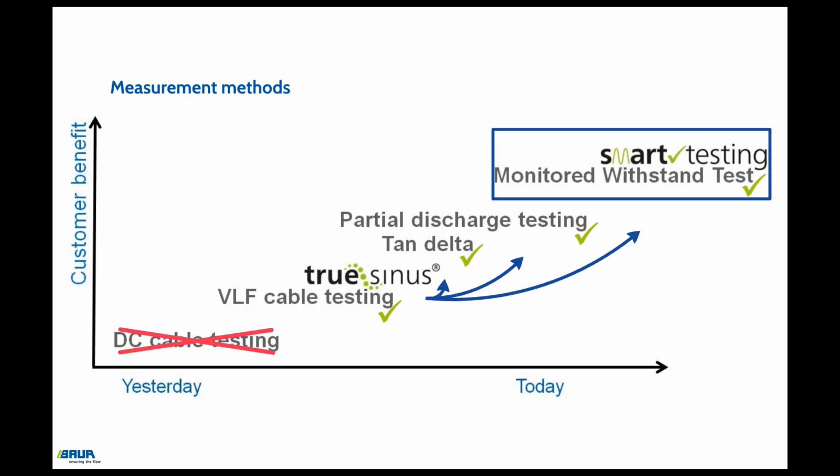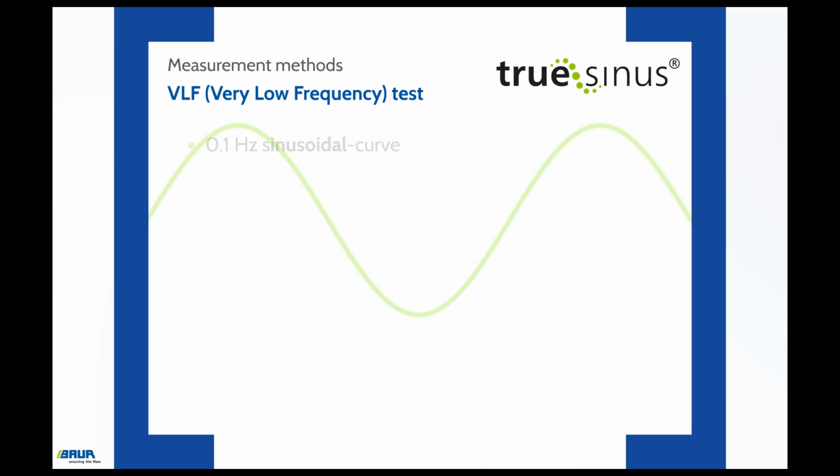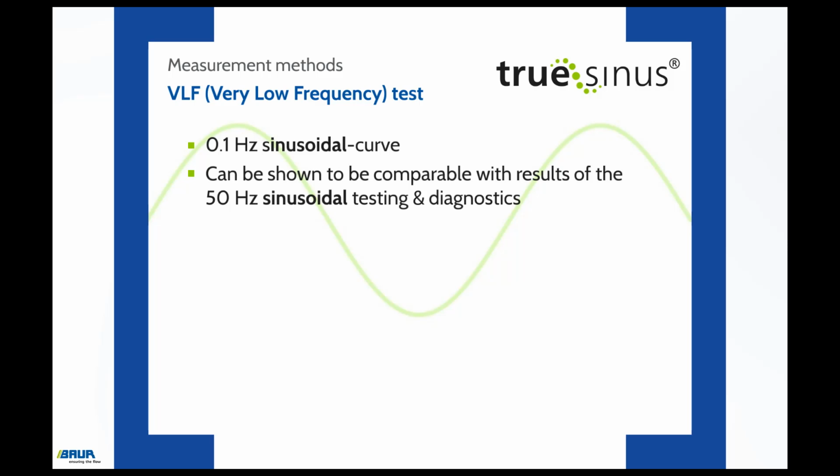It permits the least destructive cable testing and condition evaluation of medium voltage cables in compliance with VDE, IEC, and IEEE. Bauer's VLF, or very low frequency test, is based upon a sine curve with a frequency of 0.1 Hz and can be shown to be comparable with the results of the 50 Hz sinusoidal testing and diagnostics. This comparability has been comprehensively tested in practical, everyday situations by field measurements and has proven its value in numerous